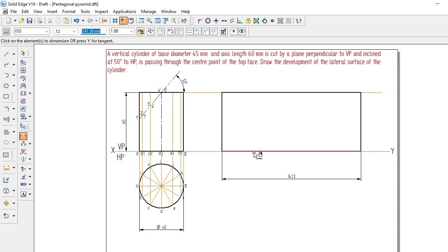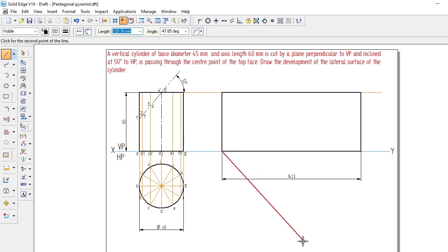After this, how to divide this one into 12 equal parts, that is these sectors here. To divide that one manually, we are drawing an inclined line. 12 parts in the sense, 12 equal parts, that line we are dividing, like this one here we are drawing the line. With 12 parts we are dividing this one, and we are connecting that line back like this, and all the lines we are connecting like this. So 12 lines we are going to get, and 12 equal parts we are going to do manually.